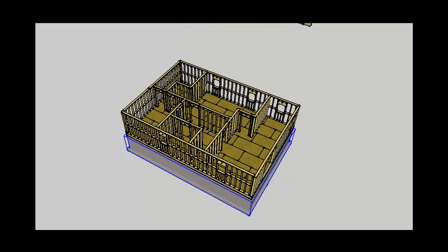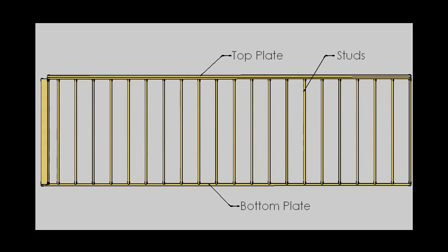They're broken down into smaller, more usable spaces, and this is accomplished by constructing separation walls, or what's commonly called demising walls. They have no structural significance. They simply provide separation of space. So, understanding the fundamental difference of these two wall types, let's go back and look at their anatomy.